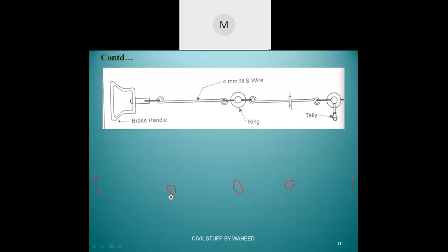This is from the 0th part. This is 5 meters, 1 tally with one tooth, and this will be 2 teeth, and this will be again 1 tooth only, because from here it is 5 meters, from here it is 5 meters, from here it is 5 meters, from here to here it is 10 meters, like that. Okay. Now for a 30 meter chain, based upon this concept, how many links will you have?